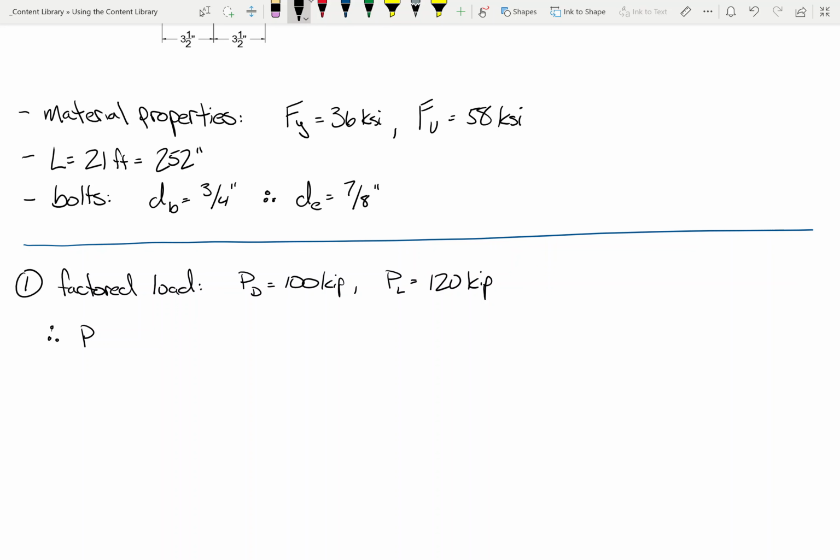Okay. And so the way I like to do this, at least the first time, is we know that the expression is a big old fraction, and on the bottom of that fraction is a denominator. So let's go through that. On the bottom, there's 2 terms. So there's 0.9 Fy. Let's go ahead and compute that. 0.9 times 36 ksi is what? 32.4.